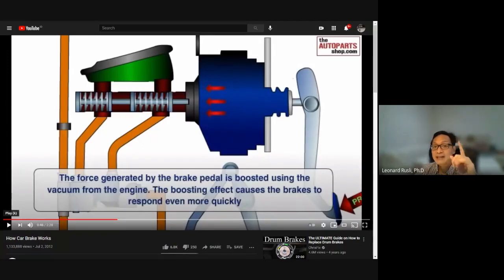Even though there is Pascal's law, so the piston size still helps, but it's not that different. I mean the piston in the master cylinder is about this big. The piston in your brakes is about this big. So it's slightly more, maybe 1:4, 1:5. But that's still nothing, right? And then you got your foot lever, this is maybe 1:4. So in total 1:4 times 1:5, so about 1:10. But 1:10 is nothing. What you can press with your leg is what? 10 kilograms.